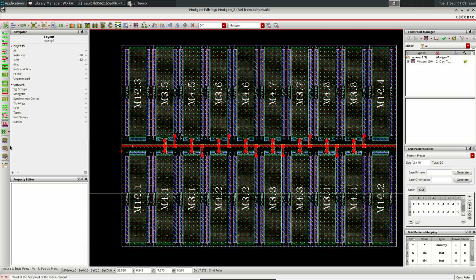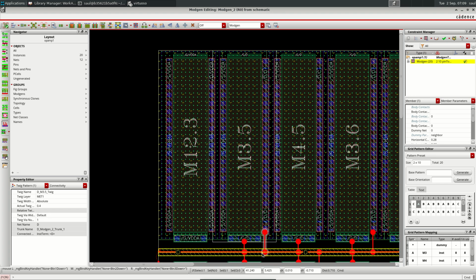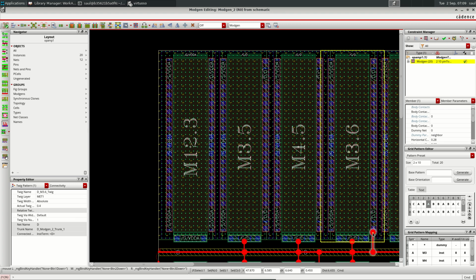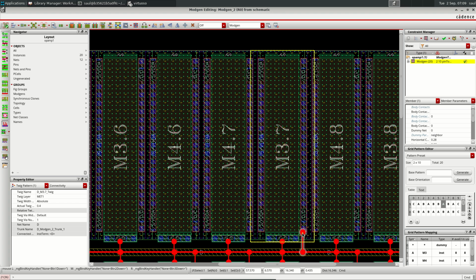For the first one, I'm going to remove the routing, so I can see only the twigs connected here, and I can remove manually these ones. Now you have to know that it is possible to configure the router not to do these connections, but I never managed to make it work properly, and it is quite fast to just do it manually. So just delete these twigs that go to the drains manually.